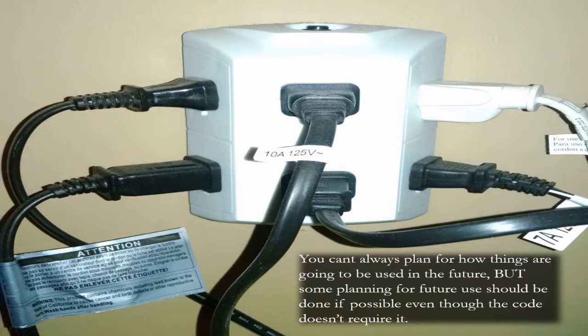Customer takes the cover plate off, puts on a new 6-way splitter, and if this was in a room that had 4 or 5 receptacles that all had splitters on them, we could be causing a potential problem. We could be overloading that circuit because it was never intended to have all those receptacles and things plugged into it. But you can't plan for that. The only way you can plan for it is if the customer lets you know ahead of time, and oftentimes they do not.